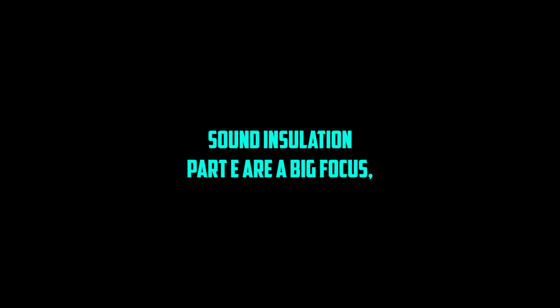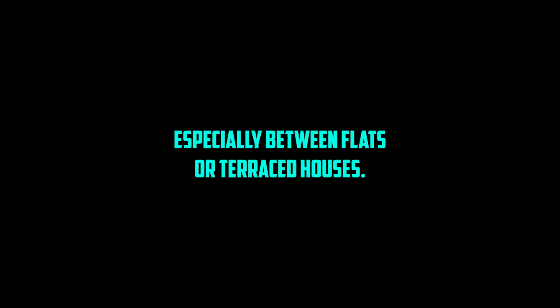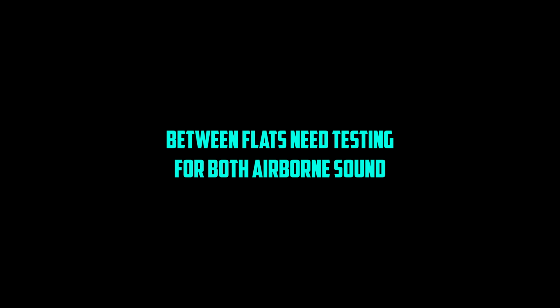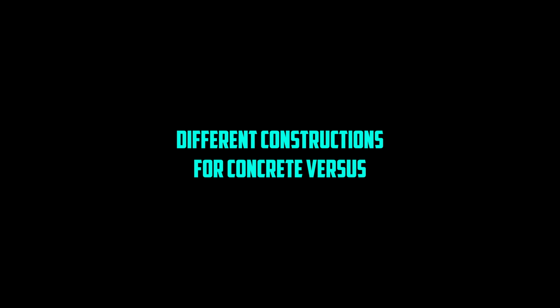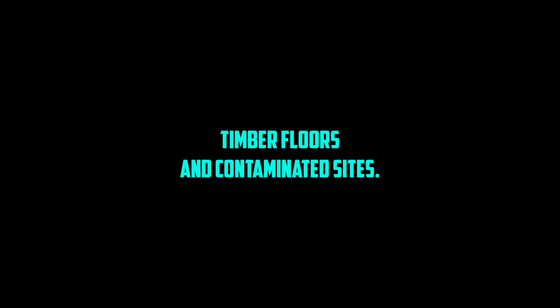Sound insulation, Part E. A big focus, especially between flats or terraced houses. Different requirements for lightweight framed walls versus solid masonry. Separating floors between flats need testing for both airborne sound, voices, music, and impact sound, footsteps. Different constructions for concrete versus timber floors. And contaminated sites again, cleanup methods.